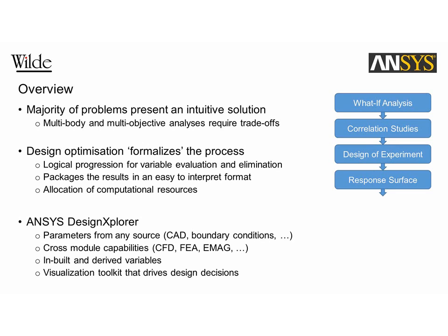Look at the response surfaces to see how the input parameters can predict the output parameters based on mathematical models. We optimize either to a maximum or minimum or to a specific target. And then we've got to do the Six Sigma or robust design to make sure that something that works in the technical world will also work in the real world based on uncertainties like manufacturing and operator handling.